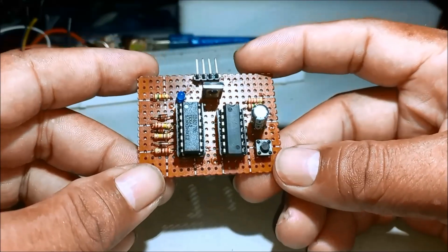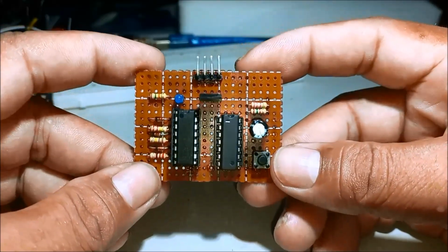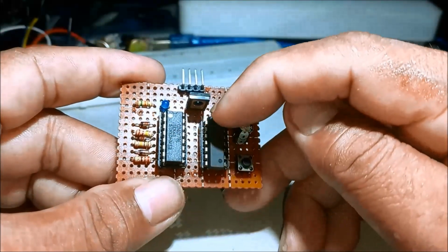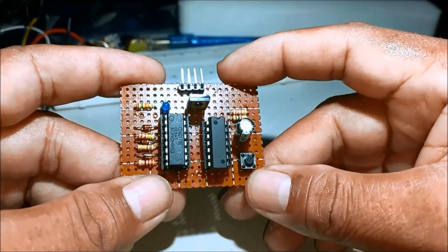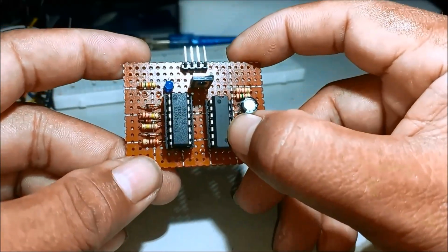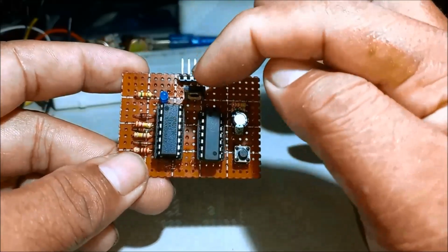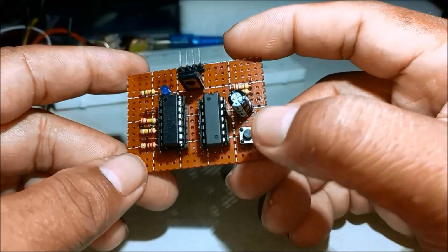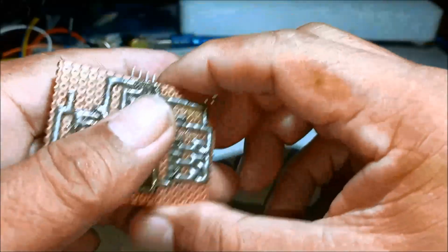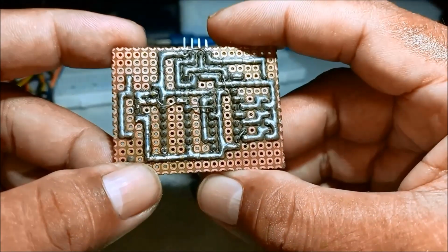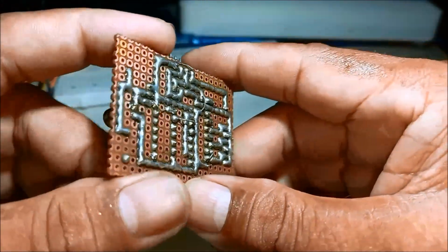Homemade DIY dimmer switch using the 4017 IC and matching debouncing IC, hex inverter 7414, driver transistor for the output COB LED, push button, and freestyle soldering, freestyle PCB layout.